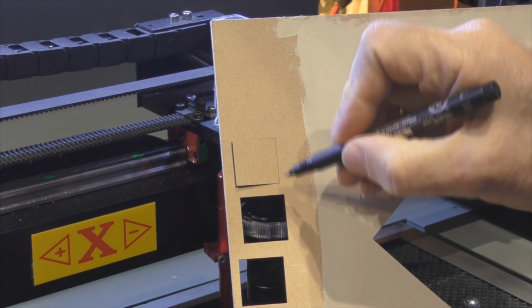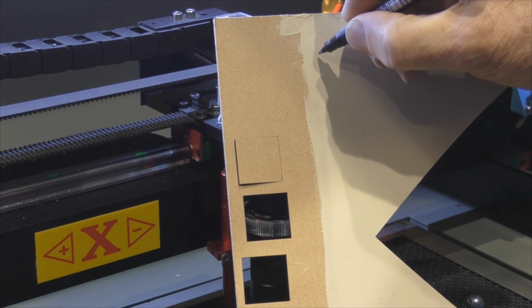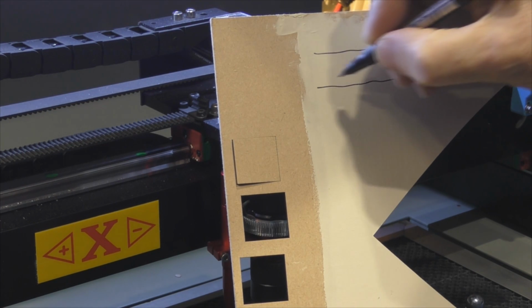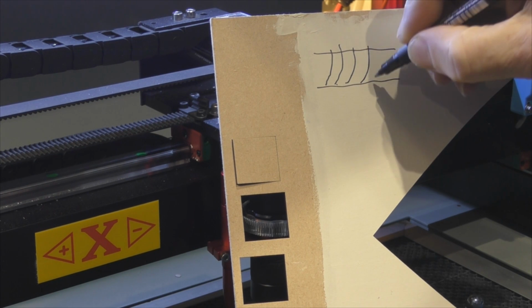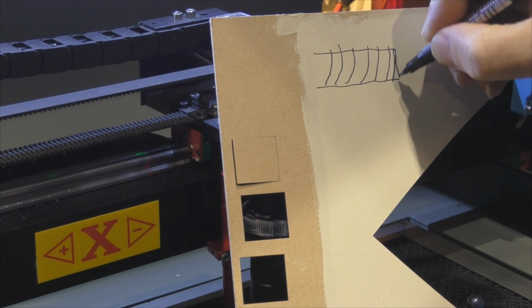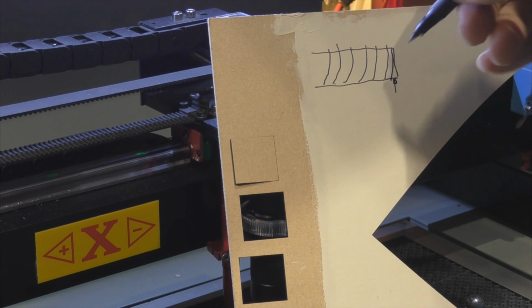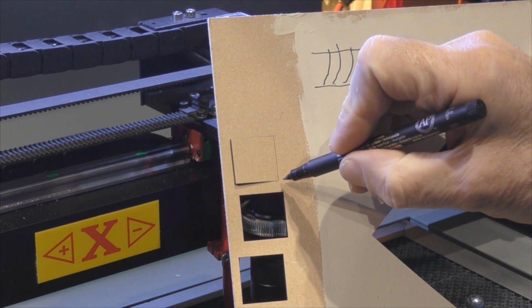We could push it to 22 and see what happens. No, it's just not falling out. I mean, it's cut through extremely cleanly on the back, but it's hanging just on these corners, because what's happening is the cut, as it travels along, is actually this shape. The beam is dragging. So when it gets to the corner, just here, there's a little bit there which is not quite cut, and then it starts coming towards us. And that's probably these little corners here which are hanging.